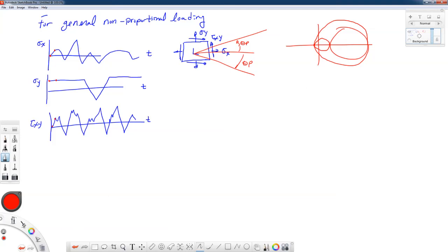So if we look at our stress block from that perspective, and we rotate our stress block between 0 degrees, if we want to call the x direction 0 degrees, and we could go all the way to 180 degrees. We could have normal stresses pulling at each of these different directions, and we could do a fatigue analysis on each plane in every single one of these different directions. Now the 0 degree and the 180 degree direction are the same, so I guess if we want to show this with symbols, let's say possible critical planes.